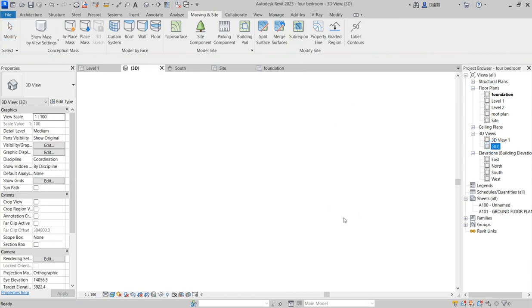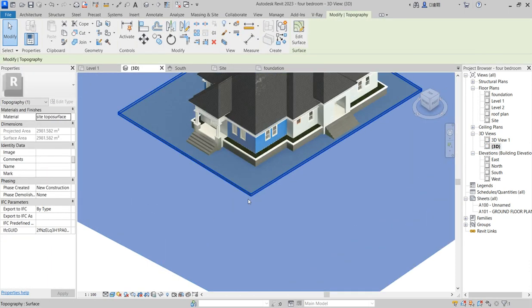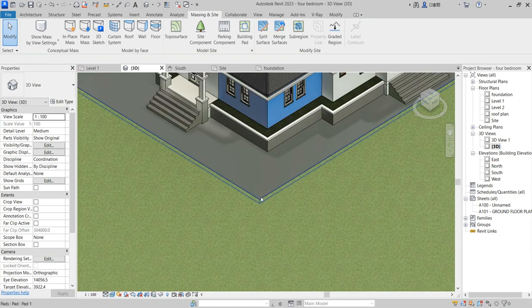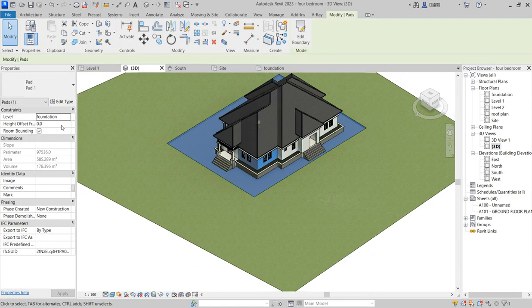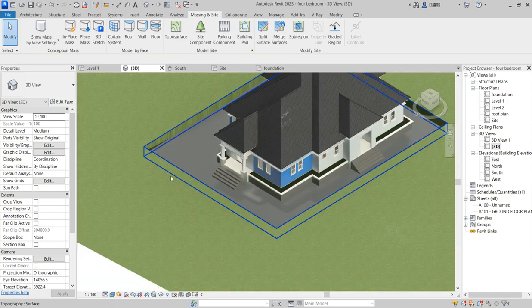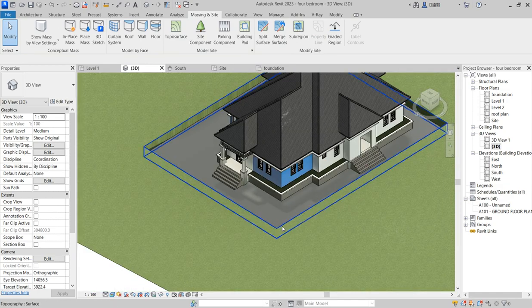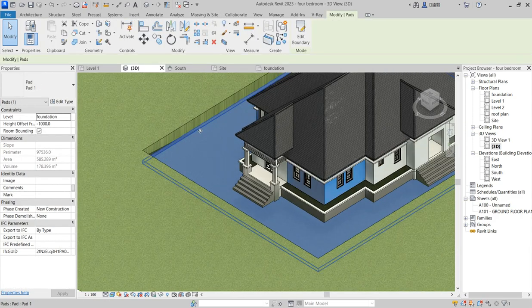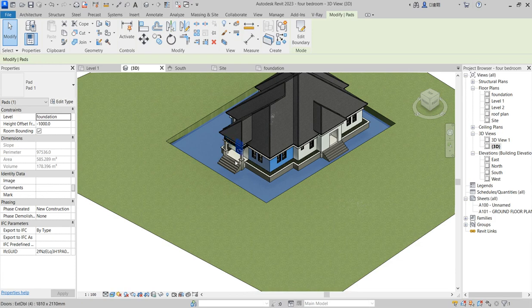When you go to 3D, you actually see what you have created. So this approach is different in method. You select this one. If you go deep down, look at it, let's see something magical. So say minus 1000 here. Now you see what we create for you. You see it bores a hole inside this place and creates its own. This is the kind of approach we use to create a swimming pool and every other thing on the Toposurface. So you can approach the same thing and do whatever you want to do.